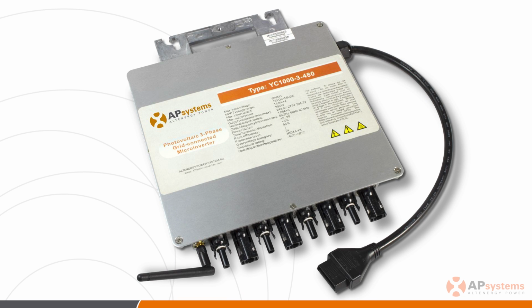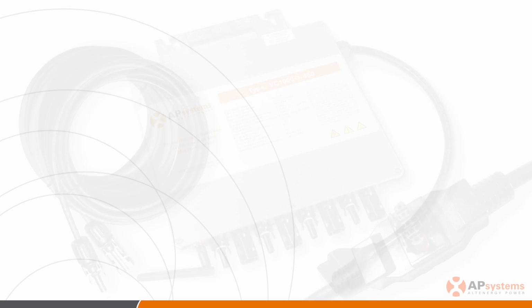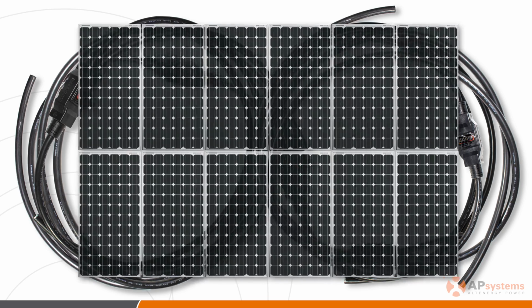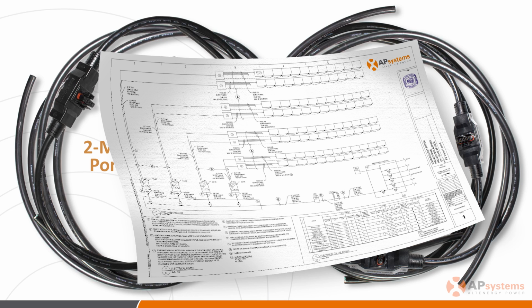Here's a picture of the YC1000 and its associated cabling. It is important to note that the YC1000 uses an AC bus cable, sometimes called a trunk cable, for AC distribution. The AC bus cable can be ordered in 2 different configurations based on the distance between the terminal connection points, which is often determined by panel orientation, portrait or landscape. It comes in both 2 meter and 4 meter spacing. Make sure to specify the spacing requirements and the number of inverter drops, which will be based on the layout of your modules in the array, when placing your order for cabling.